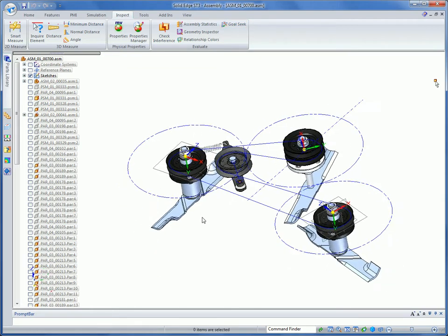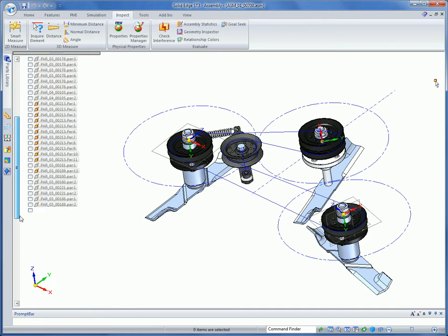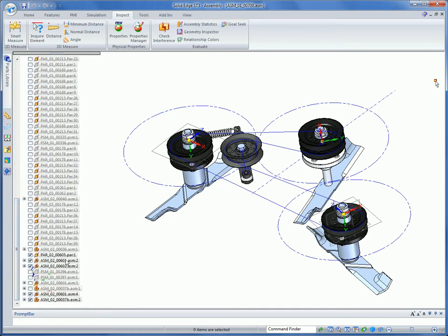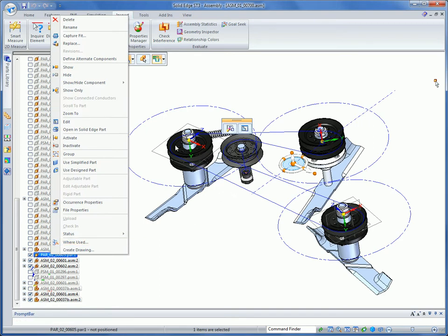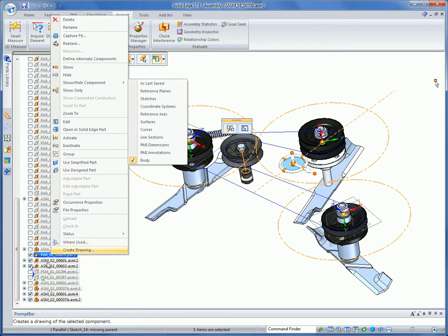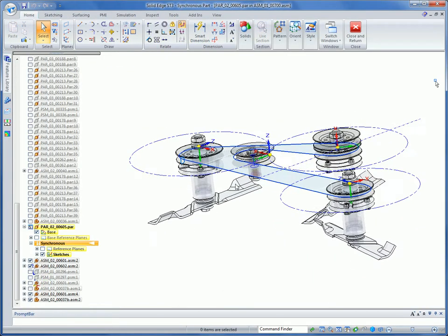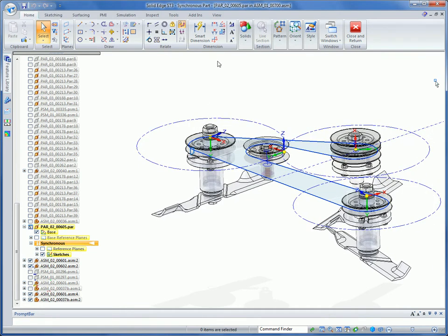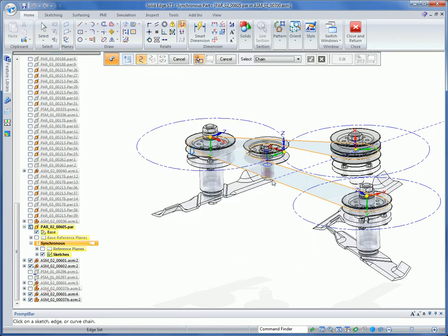The next step is that I want to create an actual belt here, and I've created a part already to save that step. I've already associatively copied in my profile. So let's double click this to edit that in place. You can see that I've got a path and a profile. So I can simply come to solids, do add sweep, and sweep this profile on this path.